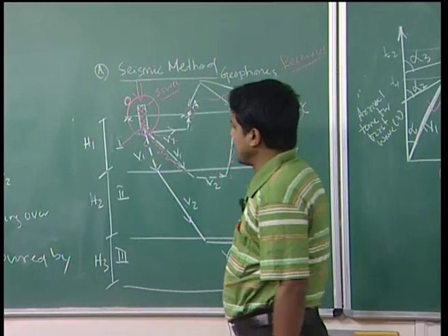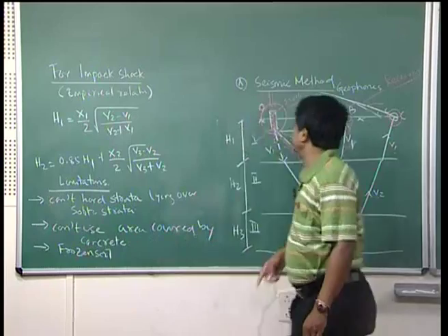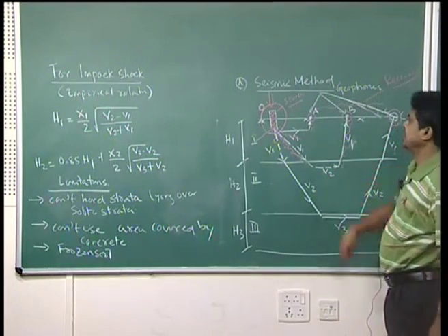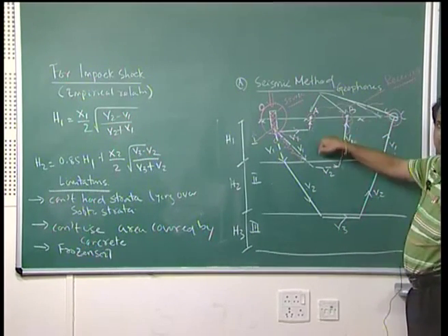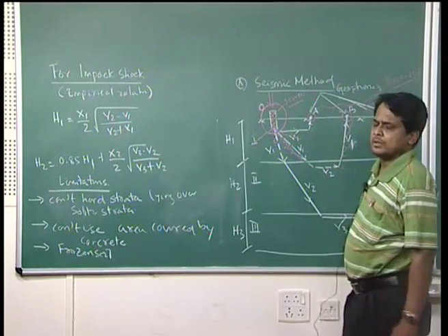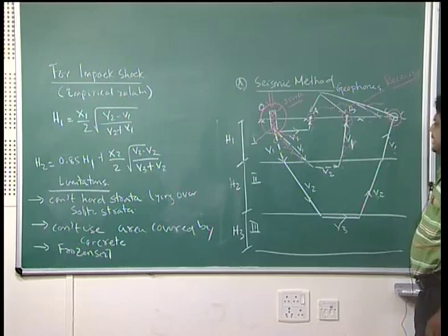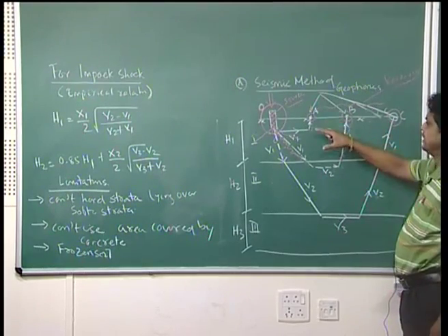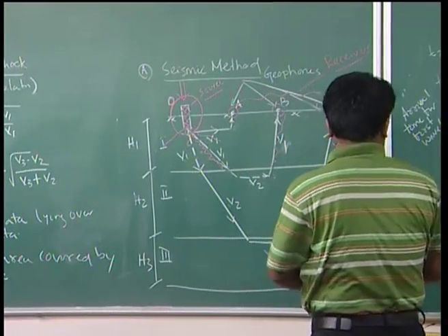Cannot use area covered by concrete. If this area has been covered by concrete, this wave may not propagate beyond the concrete. Also cannot use frozen soils. In European countries where the soil is always in a frozen state, this method cannot be used.